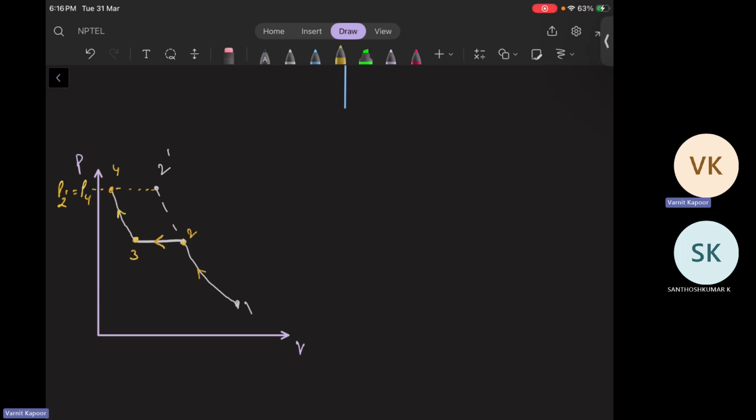And when we have increased the pressure this way, the work done has decreased. Why? If you go by thermodynamics, the compressor is an open system device, because here mass as well as energy exchange is happening. Energy means work here in the compressor. So for an open system device, the work is equal to minus VDP.